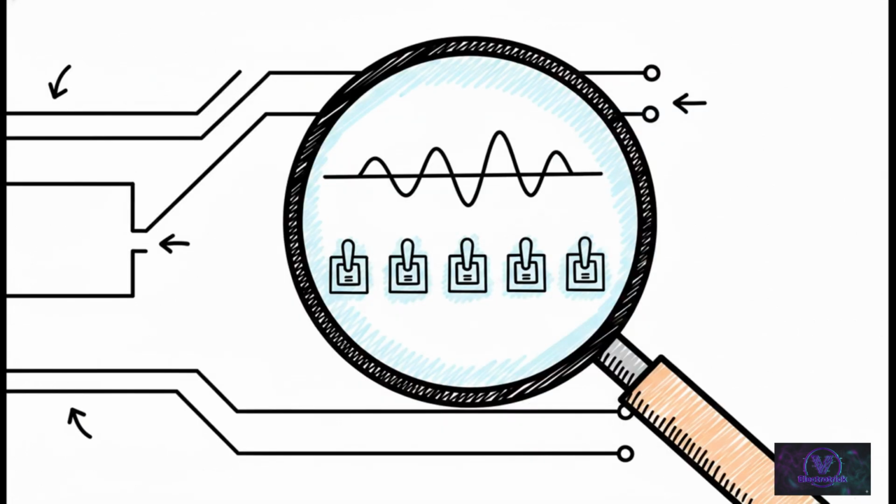Now, let's get into some actionable, on-the-job training. When you inevitably run into inrush issues in your own VLSI designs, here is your practical debug strategy. First, physically check the voltage droop during the power-up phase. Second, dig into your design and pinpoint the exact switching pattern of your power switches. Third, verify that those switches are actually staggered with the correct delays. And finally, always analyze the behavior of the nearby active logic to make sure they aren't falling victim to that charge sharing effect we talked about.